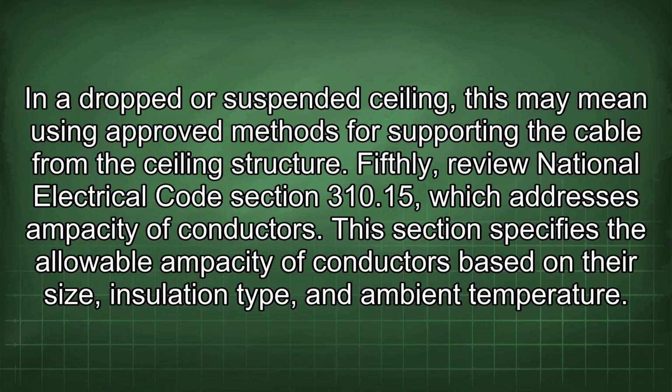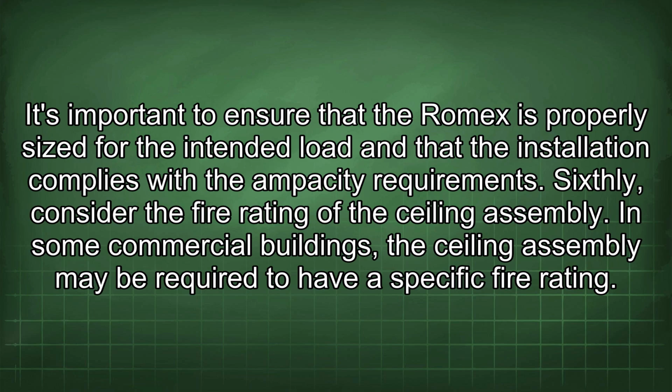Fifthly, review National Electrical Code Section 310.15, which addresses ampacity of conductors. This section specifies the allowable ampacity of conductors based on their size, insulation type, and ambient temperature. It's important to ensure that the Romex is properly sized for the intended load and that the installation complies with the ampacity requirements.